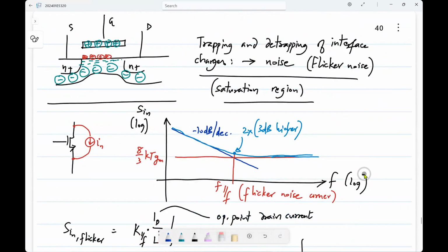If you have multiple noise sources, you do this for every noise source. You calculate the transfer functions, multiply the spectral densities by the respective magnitude squared of the transfer functions, add them all up and so on. Only thing is, you will be taking noise of one component at a time. The noise from different components will be uncorrelated, so you can just add up the spectral densities.